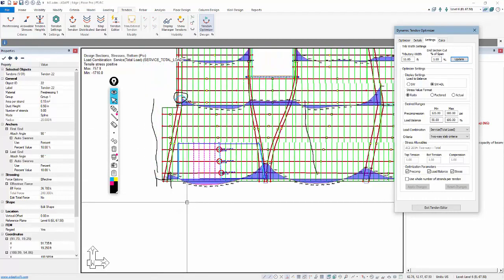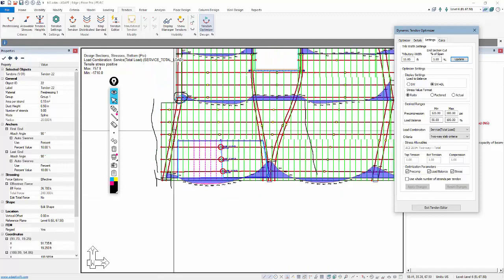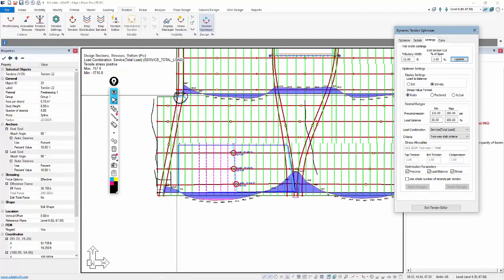And what's likely happening is it may be being referenced off of that corner of the slab. So that's something that we'll have to check. I mean, obviously there's not an overstress here, so it's not as critical here, but you want this cut to be as close to that face as possible so that you can compare it with the cut and the values that are calculated per the finite element results versus this optimization result from this actual algorithm.